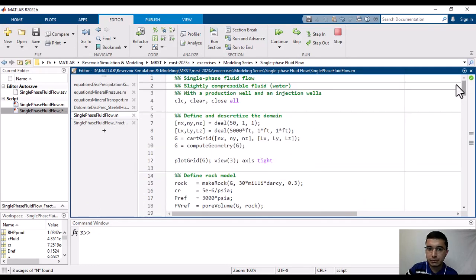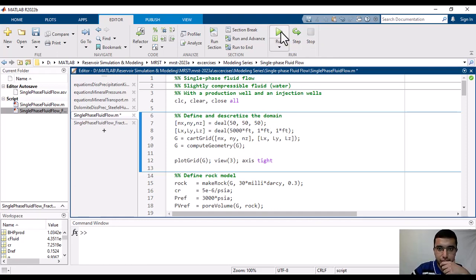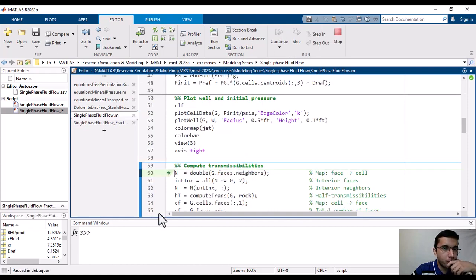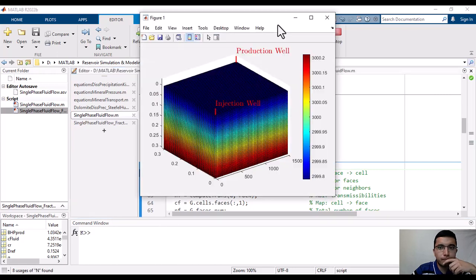But if we have a three-dimensional model like this, I'm not going to change the lengths. I'm just going to add cells. I'm just going to discretize the model in the Y and the Z direction to see the pressure change. We didn't even need to discretize the model in the Y direction because it doesn't make any changes. And as you see, there is pressure variation in the vertical direction. And as we go deeper, the pressure increases. Great.